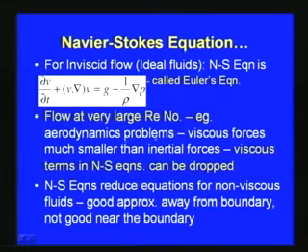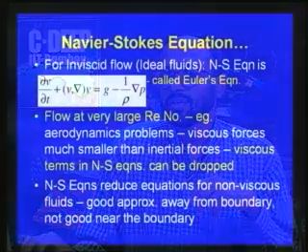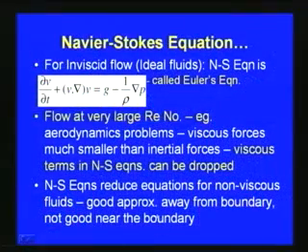So, we can say in the case of aerodynamics problems, when we consider high Reynolds number flow, we can drop the viscous terms, and modeling without the viscous terms will also be a good approximation, but away from the boundary. Near the boundary, of course, the effects will be there.